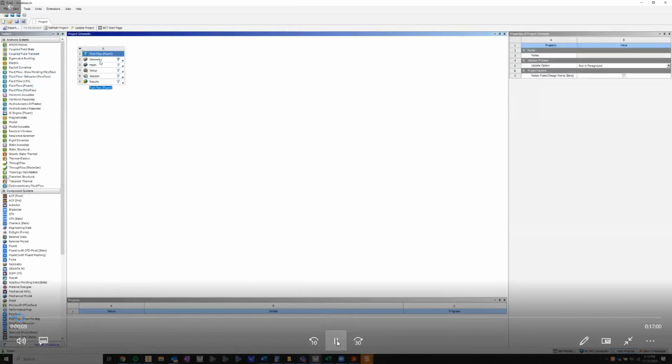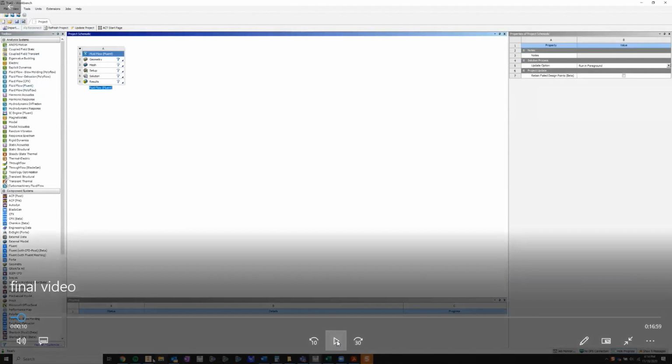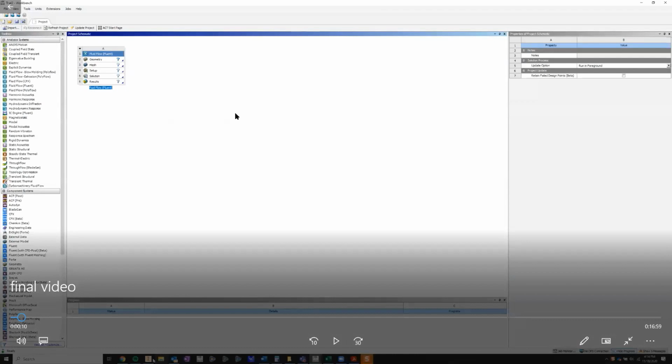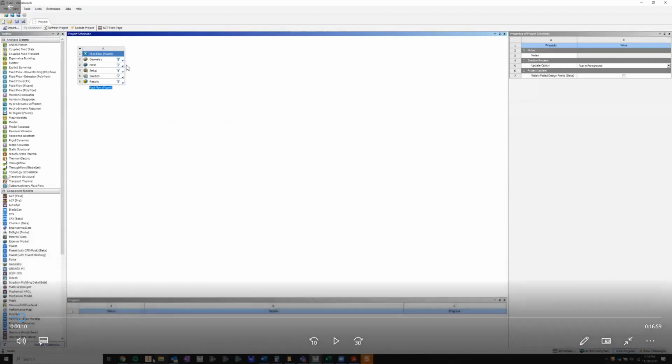complete the steps. So initially what we did was we dragged and dropped the fluid flow analysis system from the analysis system onto our project schematic. And we're going to go step by step from geometry, mesh setup, etc., to make sure that we have all the cells in order.